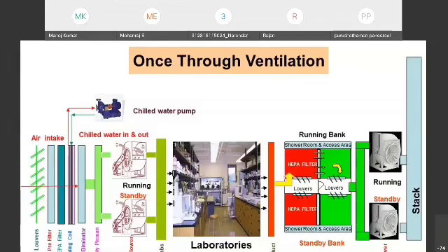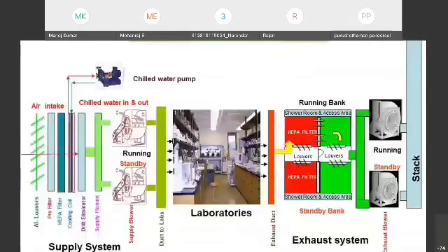And this air is again sucked through the blower through ducts, and it is supplied to various rooms through the supply ducts. We have GA ducts. Generally, the condition we maintain is a temperature of around 25 plus or minus 1 degree, and RH of around 55 plus or minus. Once this goes to the room, it cools the room, and the air temperature now increases.